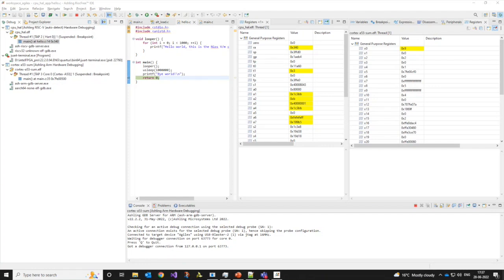And then a follow-up to the question: can Quartus Signal Tap be used simultaneously when debugging the Nios? The answer in the chat window says yes. All JTAG tools should work simultaneously with RiscFree. It'd be a matter of coordinating your Signal Tap and what you've tapped into in your Nios processor there. Okay, so I think that wraps up the questions that are currently on chat. There were some questions that came in during registration, so I'm going to go ahead and ask some of those. But audience, if you still have questions, feel free to put them in on the chat window.